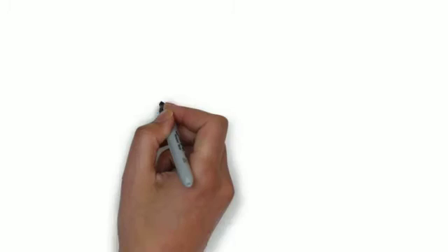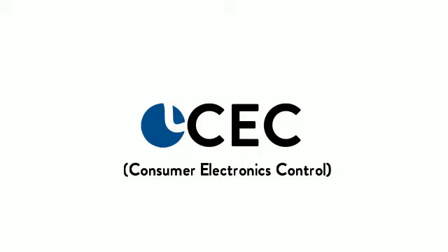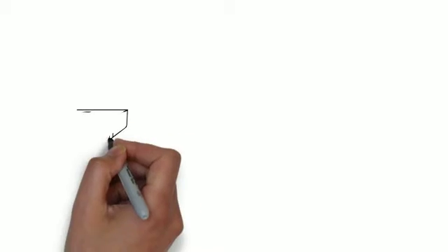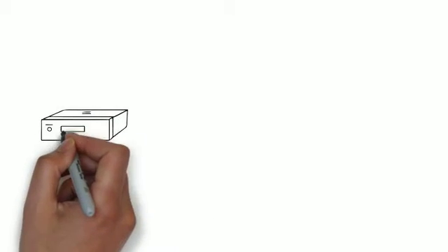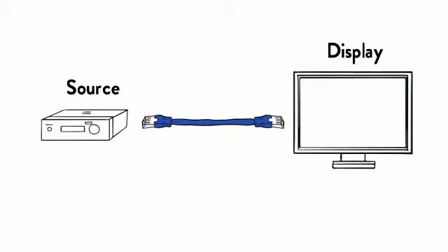Moving on to CEC, Consumer Electronics Control, the control protocol found in HDMI. CEC is a one-wire bidirectional serial communication standard. When extending the HDMI signal with HDBT, CEC is pass-through as well. Even though vendors can manipulate the CEC signal, HDBT is only the pipeline here.